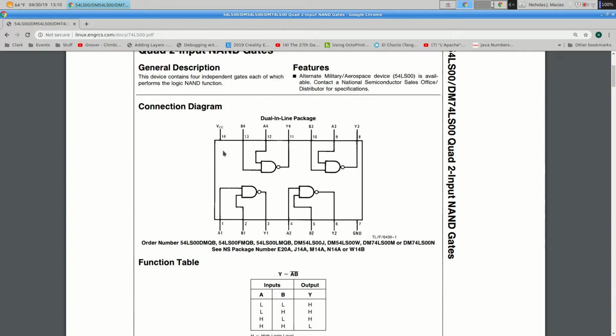All right, wiring diagram. So in this case, all of these parts have the same wiring diagram. In some cases, that's not true. In some cases, the 5400 series would have a very different pinout, right? Assignment of pins from the 7400. And the 5400 might be listed first. So if you're trying to hook up a chip, you can't just look at the first picture and use that to make your connections. Make sure that it actually says below 74LS00 right there.